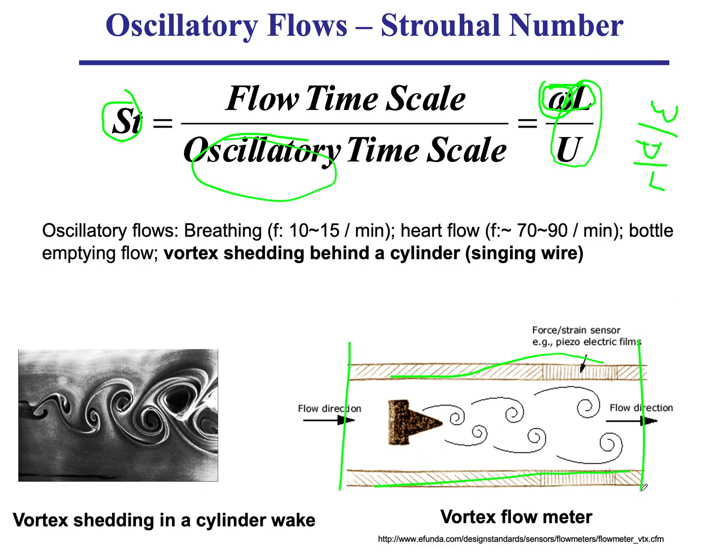It's a pipe fitting, and it actually measures the flow rate, and the essential piece of it is an object just like the cylinder. Here it has been engineered to give you a vortex shedding process of positively and negatively rotating vortices that is consistent.